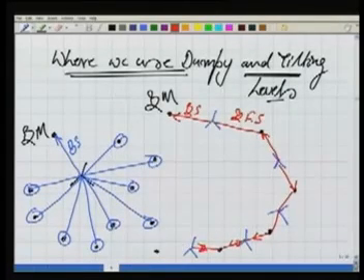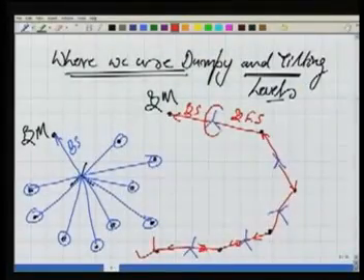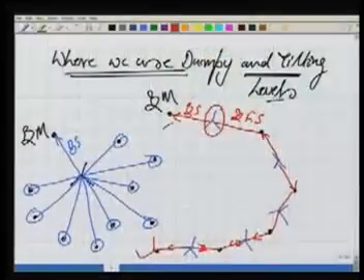So finally, this way you can determine the RL of this point. What we saw, in case of tilting level, is that we use it if at any instrument position we have to only take one backsight and one foresight, because the leveling is very quick. Just 2 times leveling, and leveling is very fast. I can very quickly take the observations here and here. I am not wasting my time in leveling my tilting level as in the case of the dumpy level.